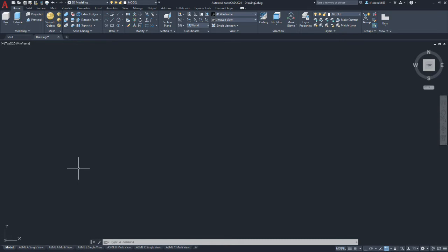So there's lots of ways to develop any of these models, but I'm going to take an approach of taking what would be the front view in my mind and starting there, because it has a pretty good section we can extrude as our first entity. So here we go. We're going to start off in world. We're going to start off in the front view, and I'm going to use a series of lines.